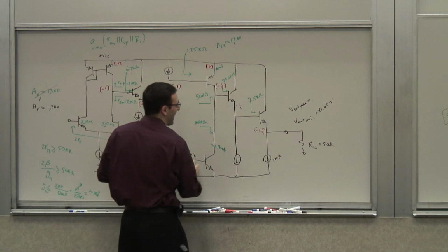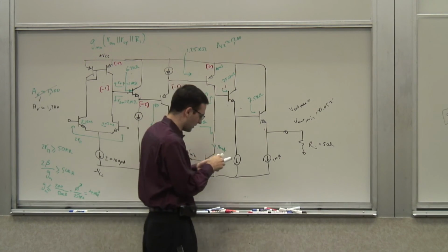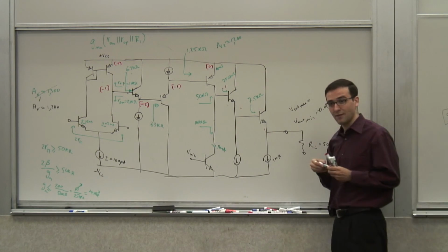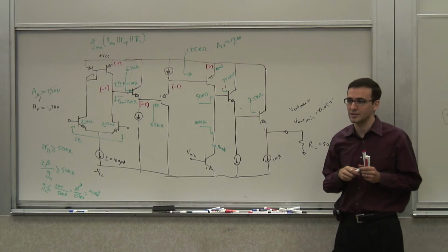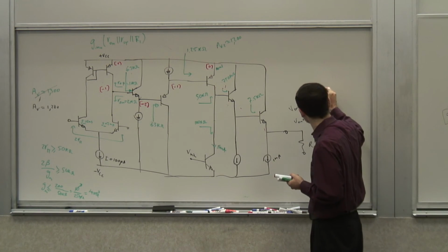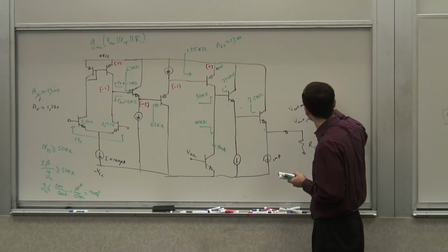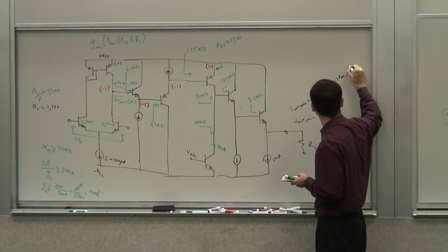So it's not as bad as the other end, but it's not good either, right? If your VCC were 5 volts now, then you are losing about 30% of it. If your VCC were 3 volts, then you're losing about half of it on that side. So it depends on what your VCC is. So in that sense, it's basically plus VCC minus VCE sat minus 2 VBE on.